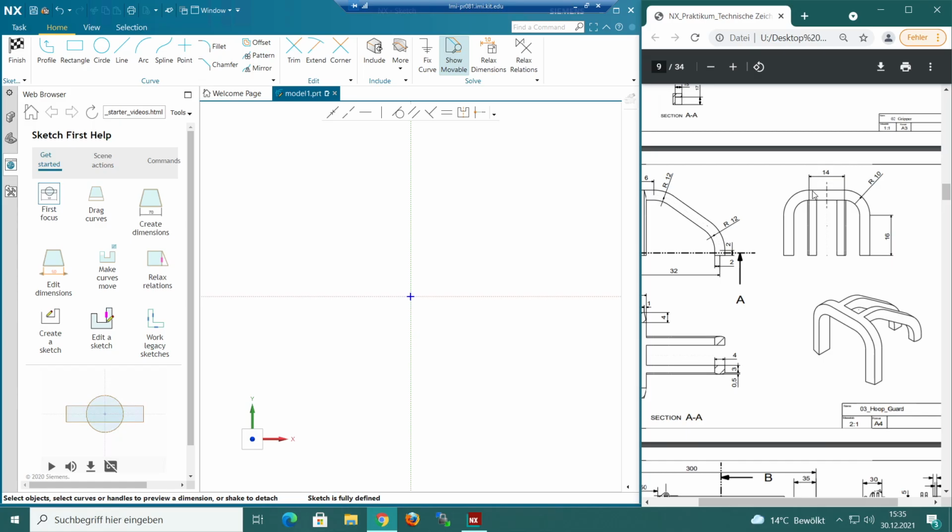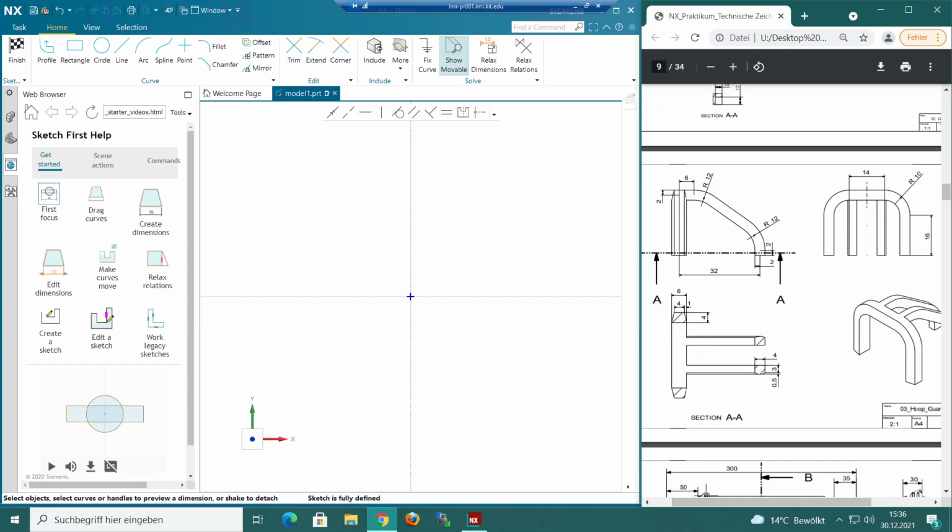So we know then that half of this is 7, because we want this distance, remember? Half of this is 7. Then we have a radius of 10, which starts right here because it's 90 degrees, as you can see. That's then also right here there are 10, obviously, and also right here there are 10 millimeters, okay? So we can just simply add 7 to the 10 millimeters, and then we already have 17 millimeters, which should be the outermost line of our sketch right here.